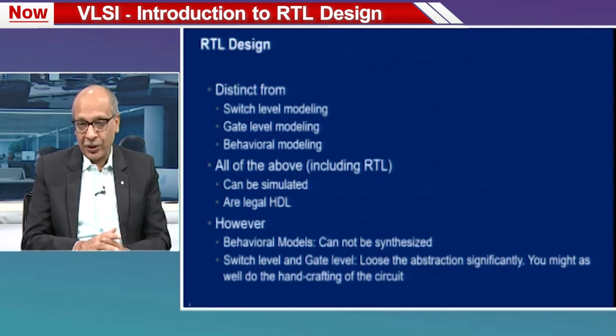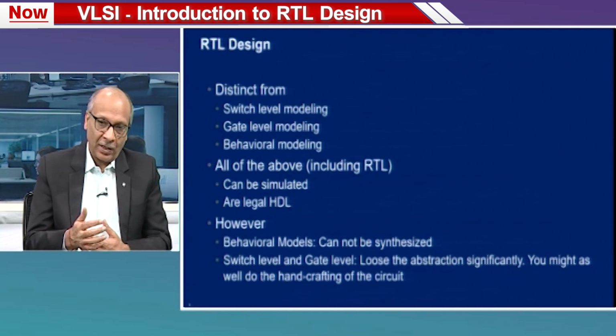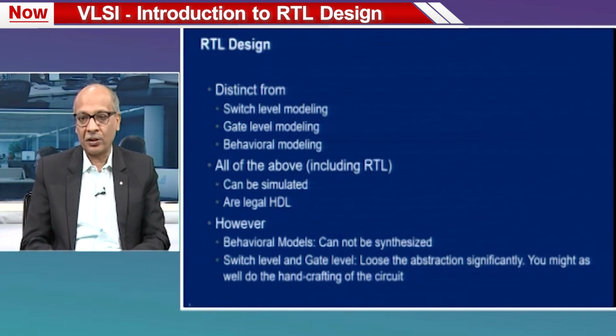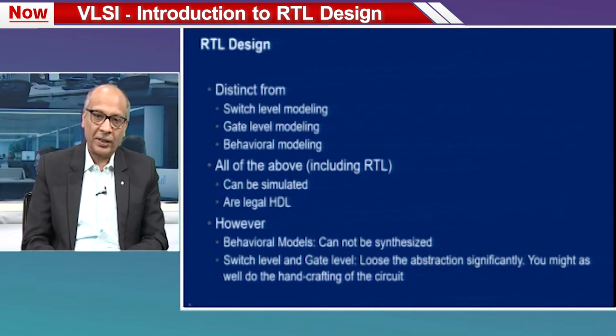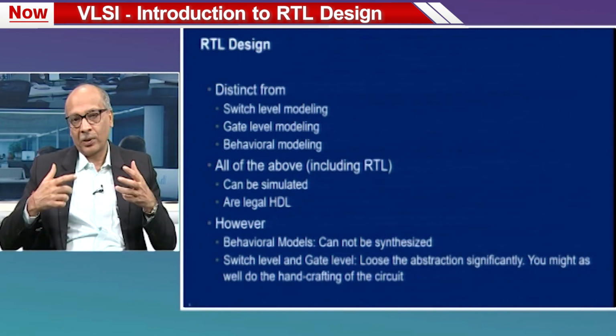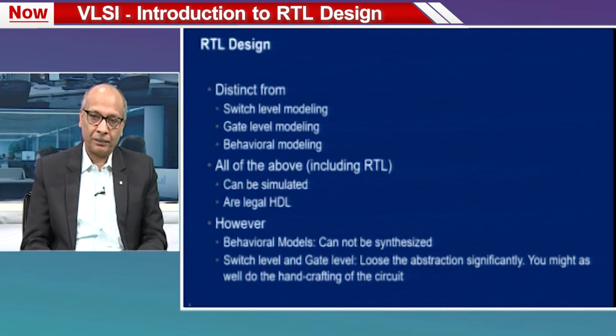However, RTL is special among these four because behavioral models, while you can simulate them, you cannot synthesize them, and we will talk a little bit later as to what synthesis means. And the switch level or the gate level do not have a very high degree of abstraction, they are much lower level designs. You might as well handcraft the circuit. So, there is no extra advantage of that methodology over RTL. This is why the RTL based methodology is much more popular in the current world of design techniques. So, let us see a little bit of what this means.